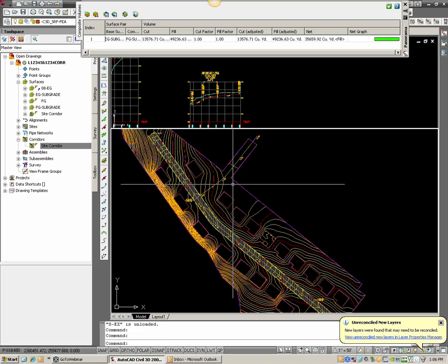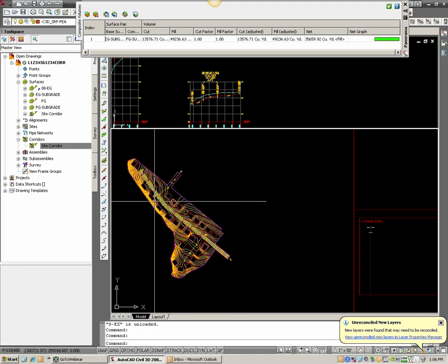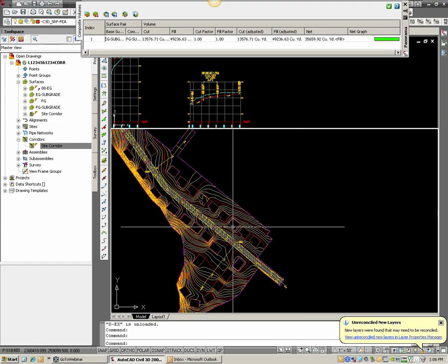So hopefully that addresses your question somewhat. But yeah, I would keep everything in the same drawing. That's what I was talking about before. A lot of times your feature lines for the grading aren't really in a grading file. They're in the corridor file because ultimately what you're trying to build is this FG. So if you break things apart in all these drawings, you have to interact with a lot of drawings just to build this one FG surface.